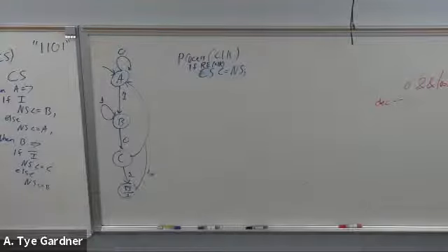If it's the rising edge, we take whatever the next state output is, throw it on here. Current state has updated, which means this process will update, right? Because if this changes, this runs. If this didn't change, if the next state stayed the same, right? We're in B, next state is B, this process won't even run because current state didn't change unless I does, right? That's how the VHDL is working. Well, there's nothing more complicated than that.